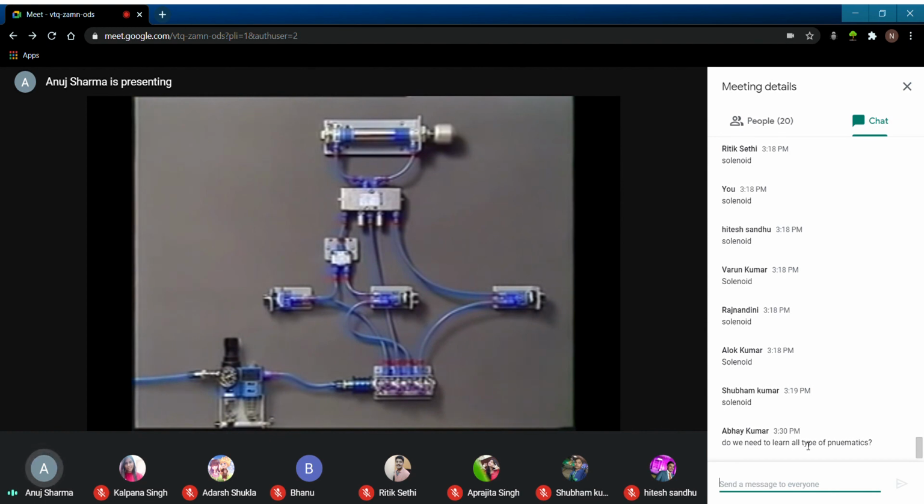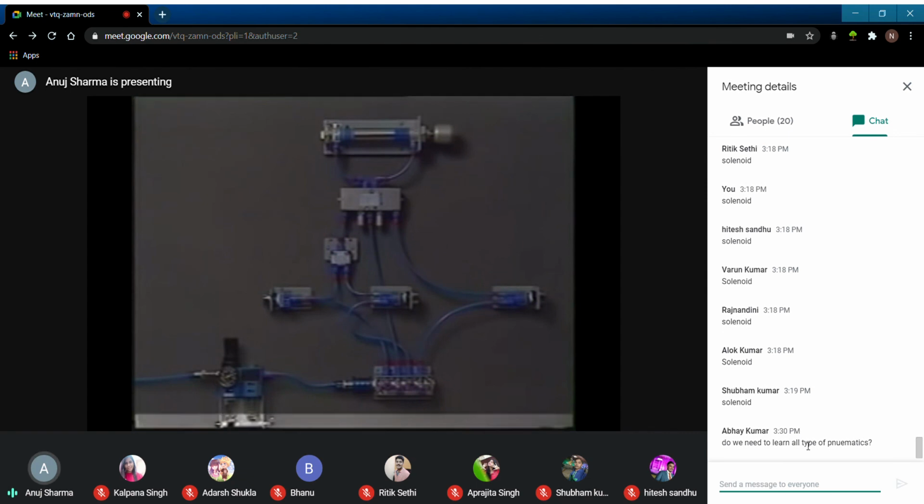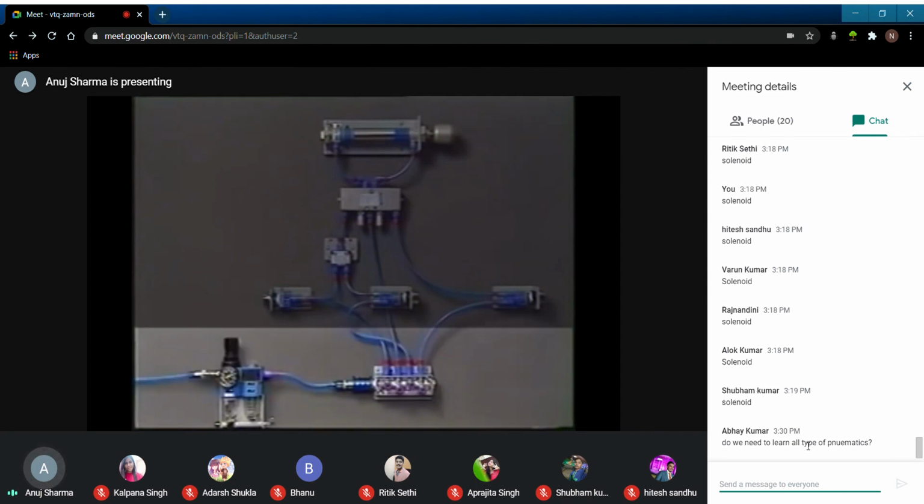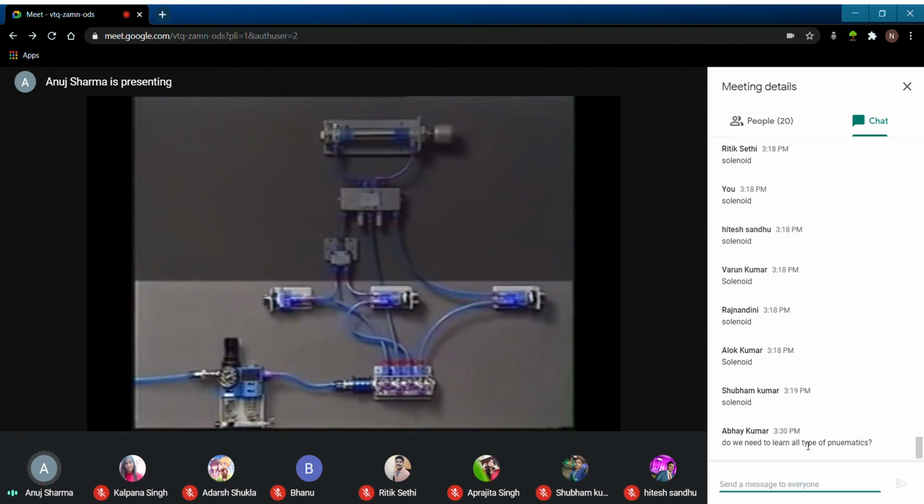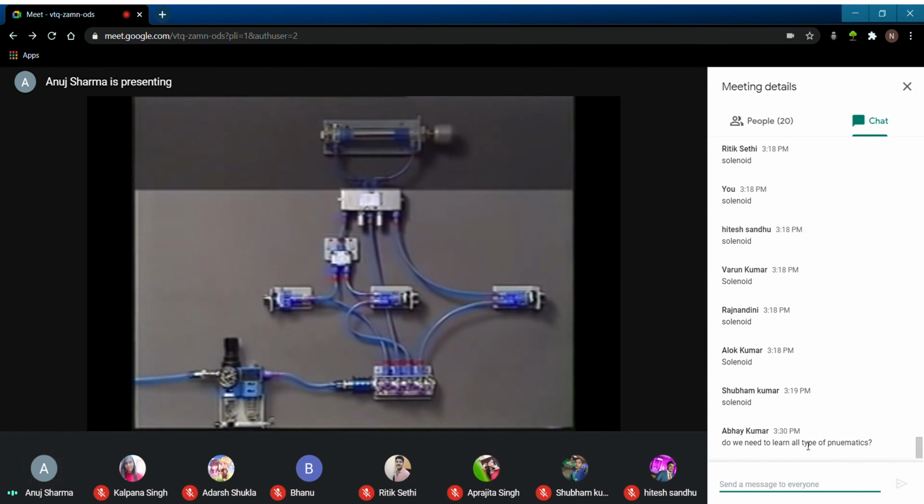The structure of the pneumatic control system can be described in terms of the functions of the circuit components. The first level is the source of energy and its preparation. The second level contains components that initiate control signals. Logic functions that process these signals are located in the third level. These determine conditions that must be met before actuators are moved. The fourth level contains control elements that send air to the actuators.